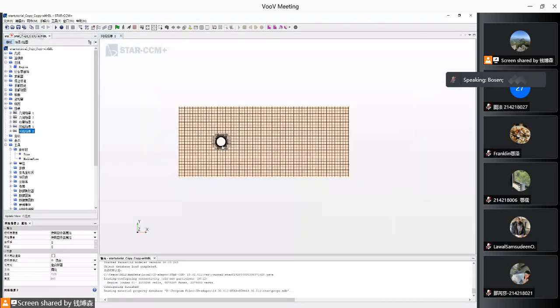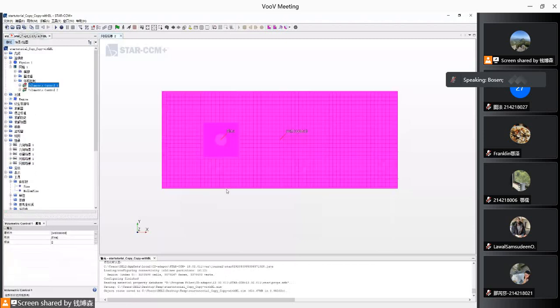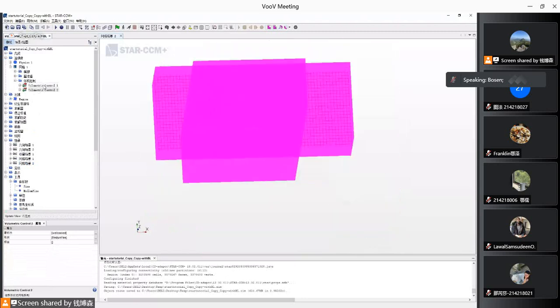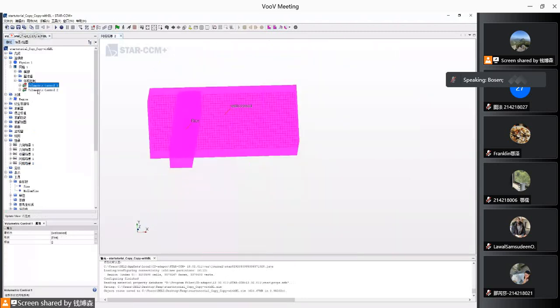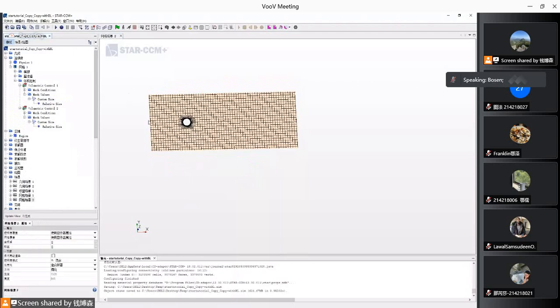Okay, so now this is the mesh scene, and let's see if I set it up correctly. Volumetric control, volume control fine, volume control medium, okay, medium fine, fine, medium fine. So this is fine. Value 1 millimeter, 4 millimeter. Okay, looks about right.